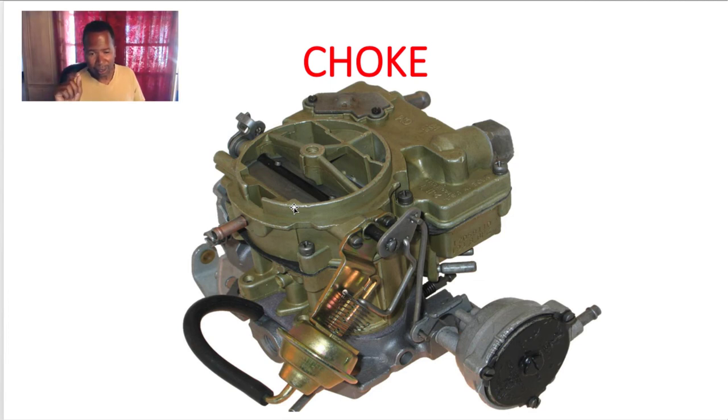This is what happens. Most people with carbureted cars, when they start their car up in the morning, have to press the gas pedal to the floor 2 to 3 times. The accelerator pump will prime the system to get it started. That's why you hit the gas pedal 2 or 3 times to start a car that has a carburetor.